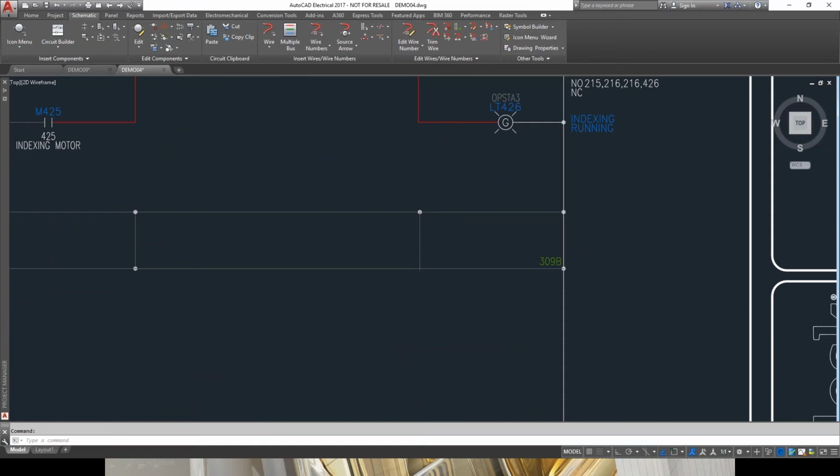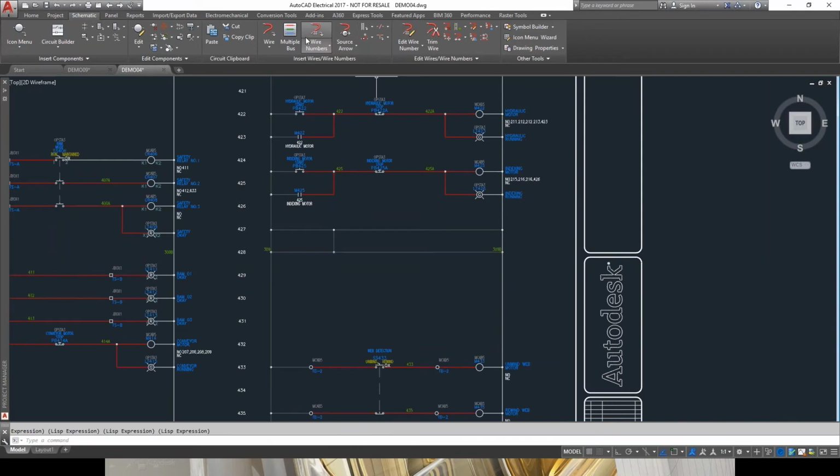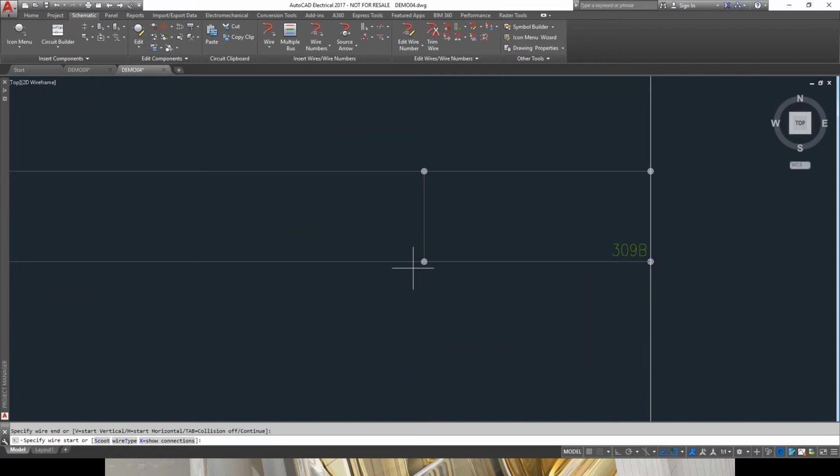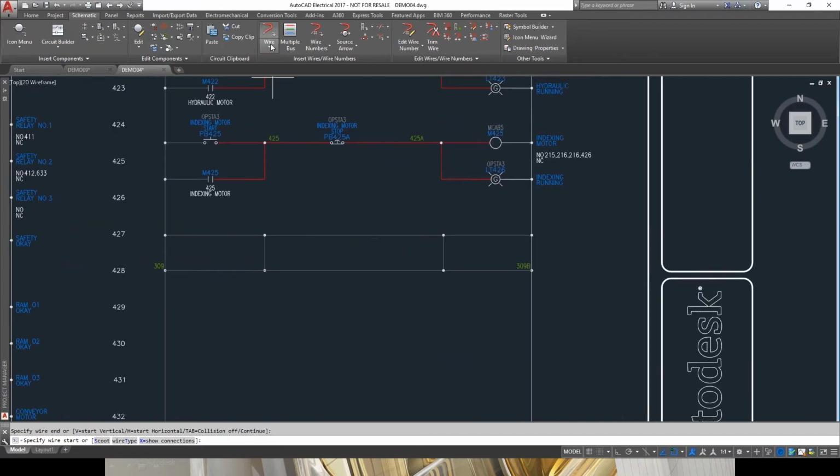So, all right, let's go ahead and draw up my control circuit some more, insert some more wires. Oops, missed my connection point there. So there is a certain trap distance you need to be within when you're working with AutoCAD Electrical. Typically we don't use O-snaps at all. Just as long as you're close enough to that certain trap distance, it will notice those connection points for you. All right, so trim this wire away here.